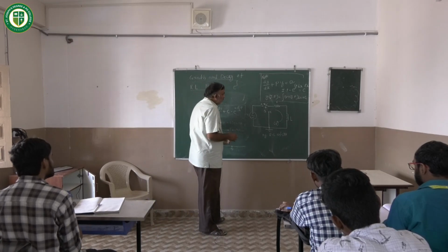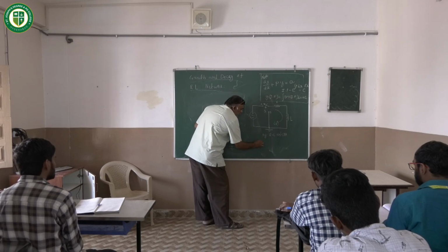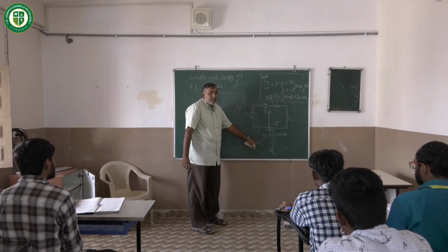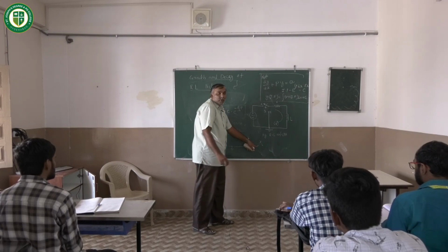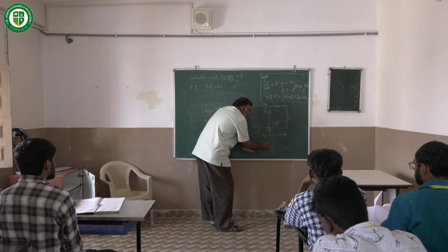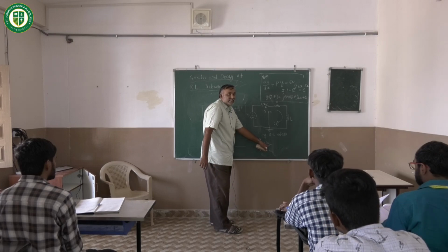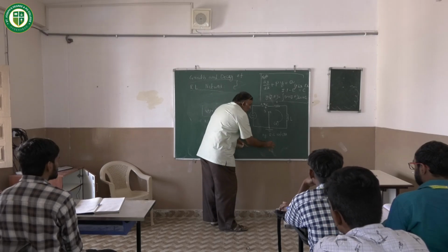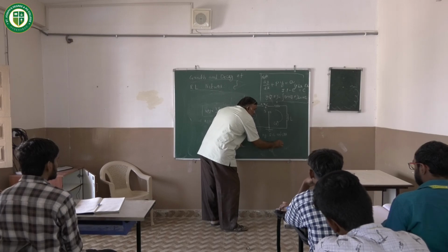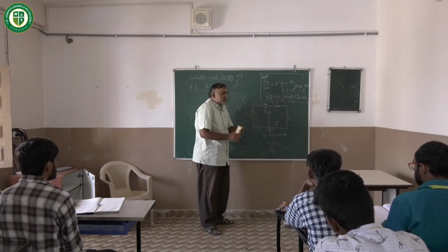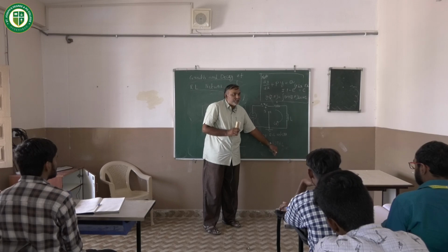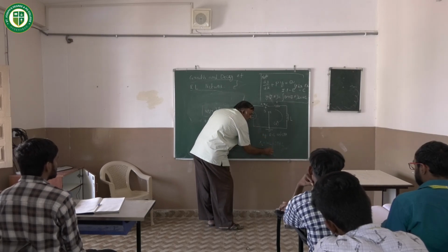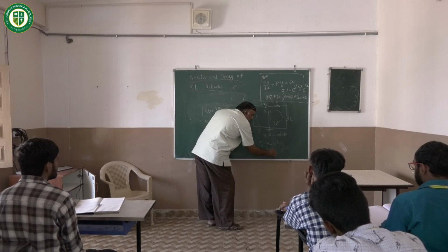You are very much clear that an inductor is a reactive element whose reactance, denoted by XL, is simply equivalent to omega L, where omega is the angular frequency and L is the inductance of the inductor. Omega is equal to 2 pi f. You are very much clear that 2 is constant, pi is constant, L is constant. So thus, XL is proportional to f.